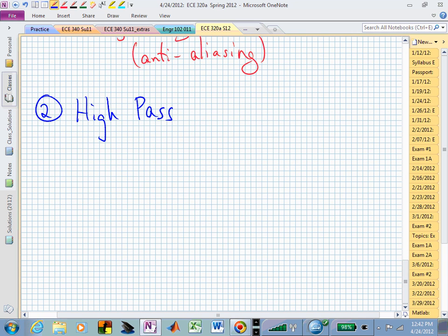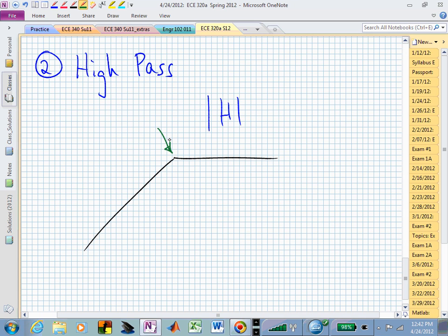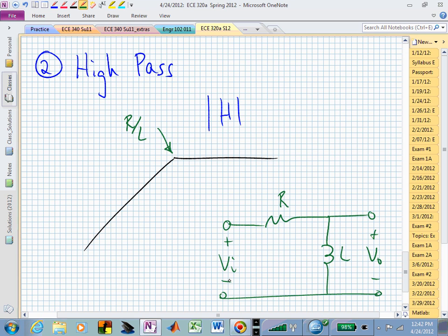In this case, again, we have 2 lines, and let me just create this one out of a slightly different circuit, where now let this be R over L, and my circuit now that would allow me to favorably pass high frequencies versus low frequencies between the input and the output in a passive circuit would be this RL circuit that I've just sketched.